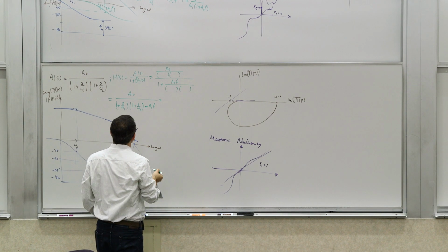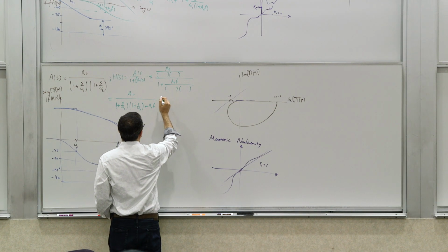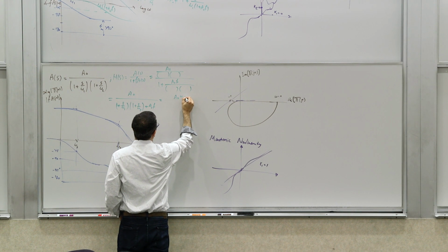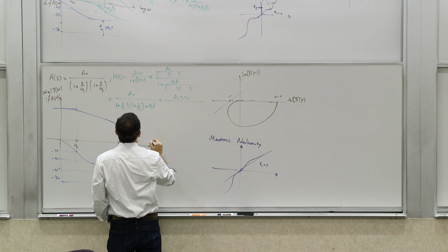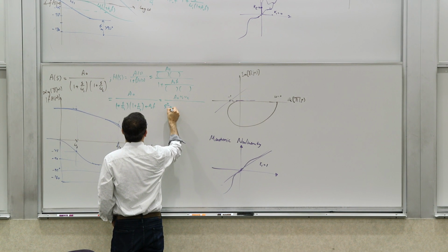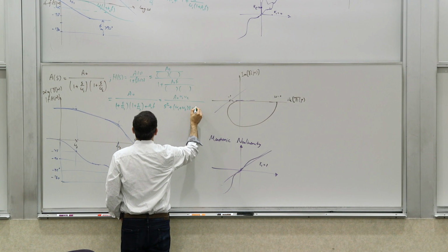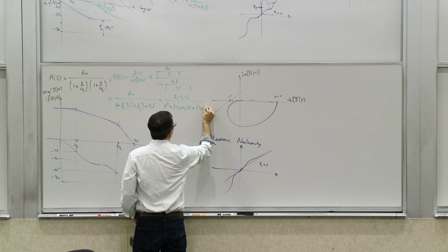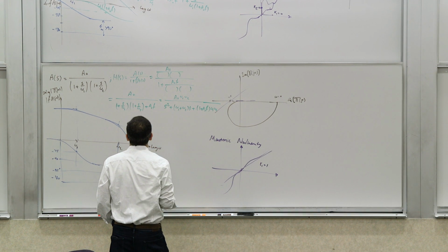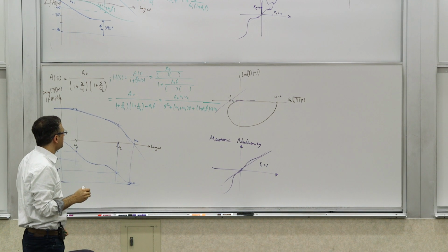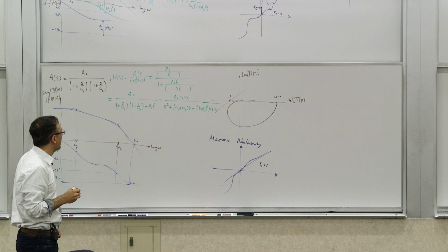which we can simplify. If you multiply both by omega 1 and omega 2 as well, you will get A0 omega 1 omega 2. You're multiplying the numerator and denominator by that. What you will end up with is s squared plus (omega 1 plus omega 2) s plus (1 plus A0f) omega 1 omega 2. Okay? So it's just simplifying that.